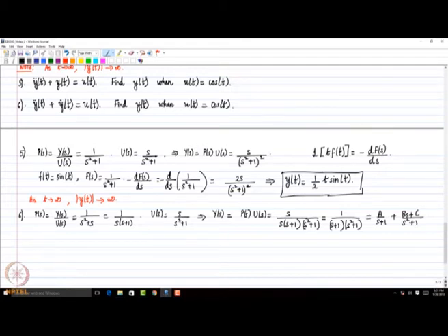Am I right? There will s equals 0 be a pole? Okay, we are coming to that. We'll discuss that. I was waiting for someone to ask me that question. That's a good point. Interpreting the question, he's asking, would s equal 0 still be a pole, because I cancelled an s and an s in the denominator and the numerator. s equals 0 is still a pole.